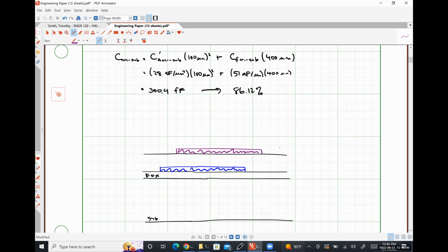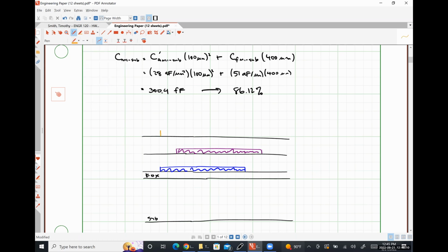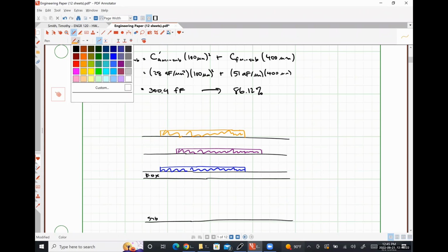Like so. And up here is going to be where our metal 3 layer will exist. And effectively what we're doing is we're making kind of a stylized capacitor sandwich, but we need to make sure that we have a connection between the various layers.